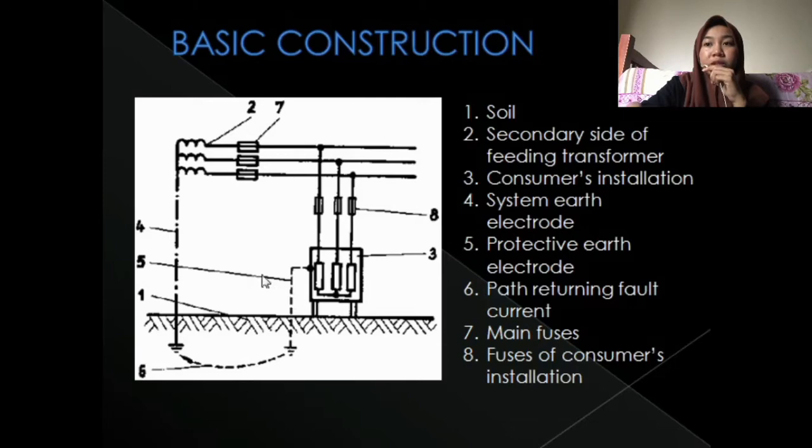So for transferring electrical current into the ground, all conductors are used which have a well-conductive connection to the ground. Earthing electrodes are either dug into, driven into, or placed in a borehole in the ground to complete an earthing system. Ground is made of the soil.